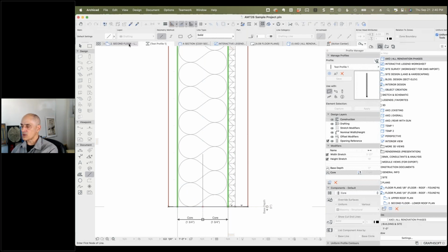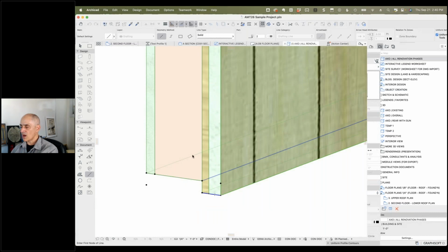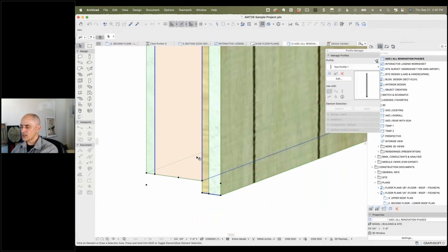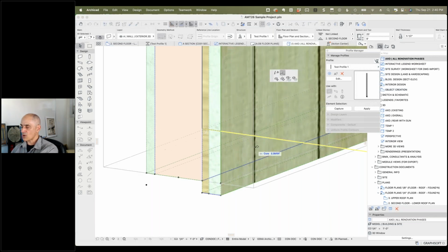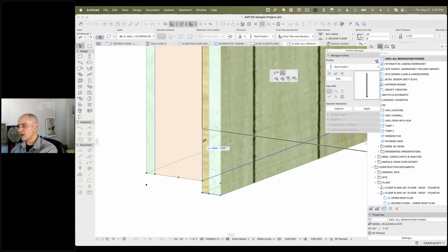And if I were to go to that 3D view and select it, you can see the blue lines here. If I were to pull this offset, you can see how it's moving in opposite directions. So right now the offset is 1 3/4. Let me make it, we're going to add another 2 inches to make it a 5.5 inch thing. So I'll say the offset will be 2 3/4.